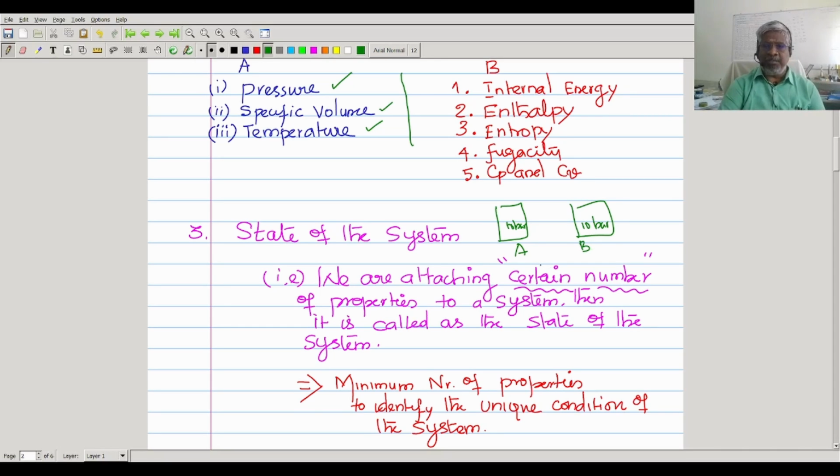No, it's not possible to say, because though I know that the same oxygen is here, I may have a different temperature: this is at TA, this is at TB. So now I can say uniquely, yes, I can calculate all other properties using this pressure and temperature of A. Now I can say that it is unique.